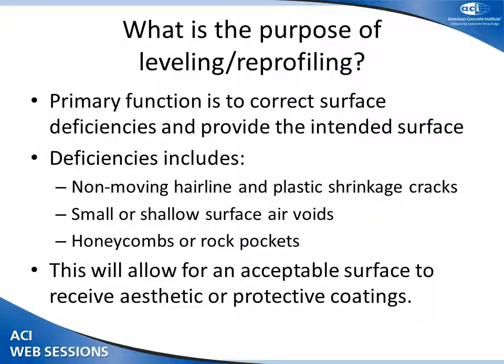So what is that purpose? Again, provide a suitable surface, repairing the deficiencies so that we can put on a protective or aesthetic coating. What constitutes deficient surfaces? Non-moving hairline cracks or plastic shrinkage cracks. These are non-full depth cracks. Shallow or small surface voids. Small honeycombs or rock pockets. Here you want to make sure an engineer validates it's just a cosmetic deficiency and not a structural deficiency. And then again, this will allow us to put on a protective or aesthetic surface.